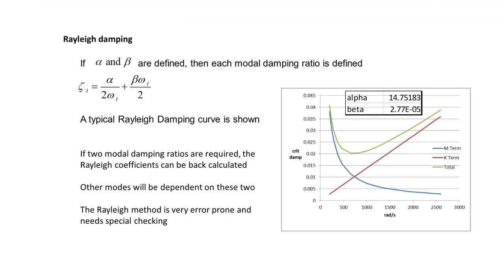Well, it's not quite a quadratic. We can think of it like, let's say, a polynomial function. We're describing damping as a function of frequency, dependent on the coefficients we use to describe that equation. If we make mistakes in those coefficients, then our damping curve can be all over the place. So if I have Rayleigh damping coefficients alpha and beta, I normally like to go to an Excel spreadsheet, plot them out to see what that damping looks like, and then see where it intersects my main frequencies of interest. I prefer to use either structural damping or modal damping.